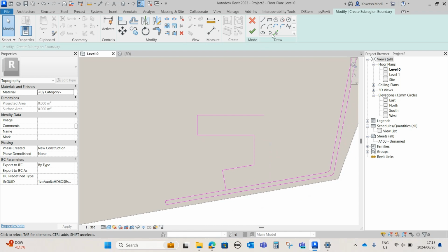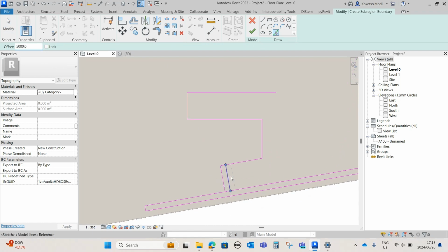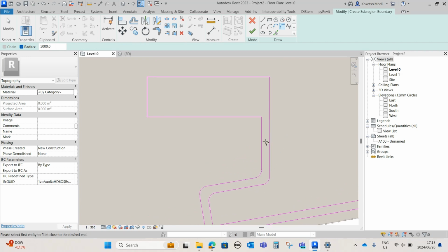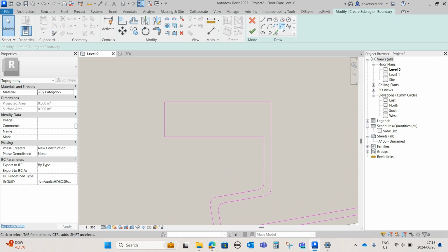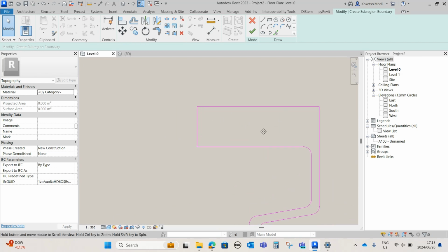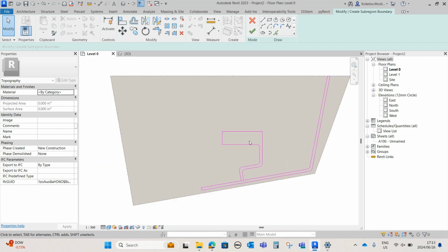and I'm just gonna leave it like that and say pick lines, and then I'm gonna offset it by 5,000 millimeters on this side, and then I'm gonna say trim and extend on also this side, and then I'm gonna apply my fillet arc of 5,000 millimeter radius. So it's going to be set like this, and also on this part. Perfect. So this is where our site office parkings are going to be situated.